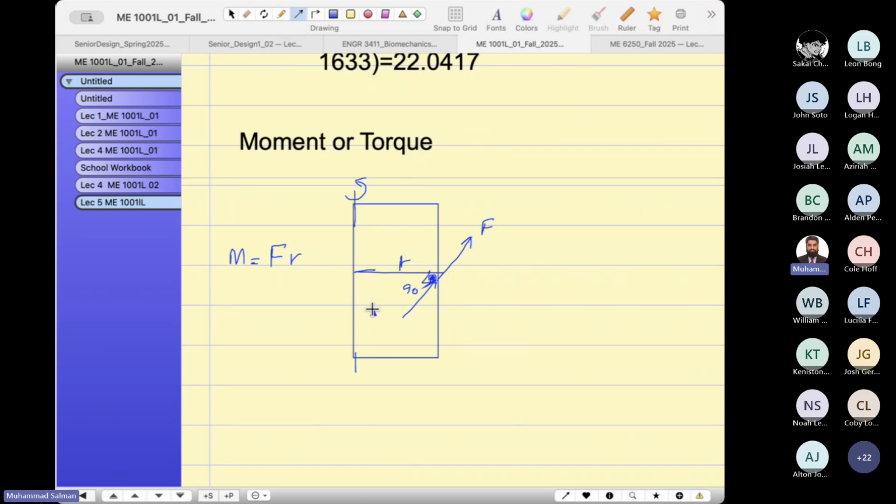If you keep on decreasing the moment arm until you hit the hinge, the door will not rotate at all because R is 0. When you touch the axis or the hinges, R is 0. So when R decreases, you are decreasing the moment.